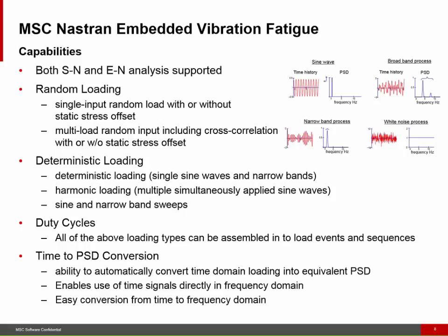So that enables an easy conversion from time to frequency domain so that time domain signals can be used directly in frequency domain. So if you have your traditional fatigue calculations set up in time domain, we have an easy way to convert into frequency domain using the time to PSD conversion.